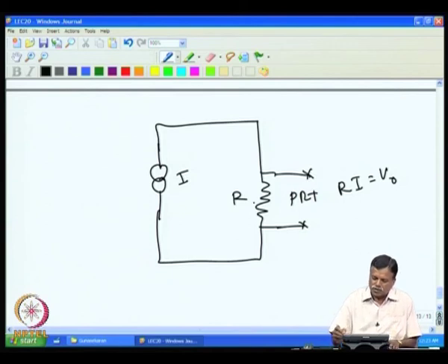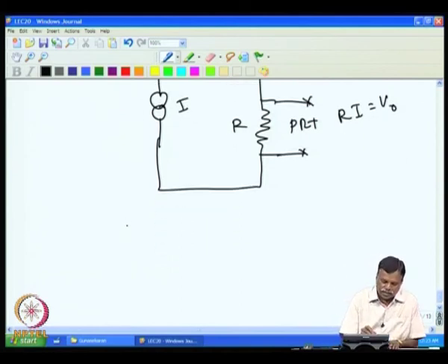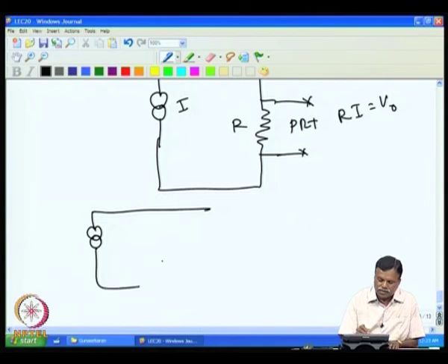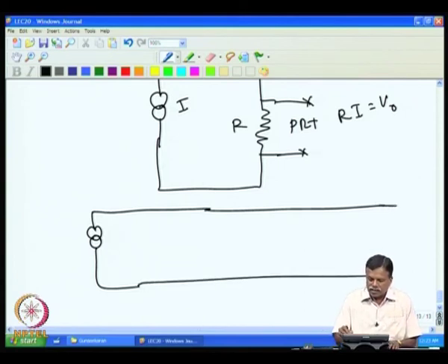In this case also, one can use a 4-probe method. For example, a Platinum resistance thermometer in real life looks like this. You have a current source coming from an instrument, and the Platinum thermometer may be at a long distance, maybe inside the oven whose temperature is to be measured. So, we put a long wire and then connect the Platinum thermometer here.